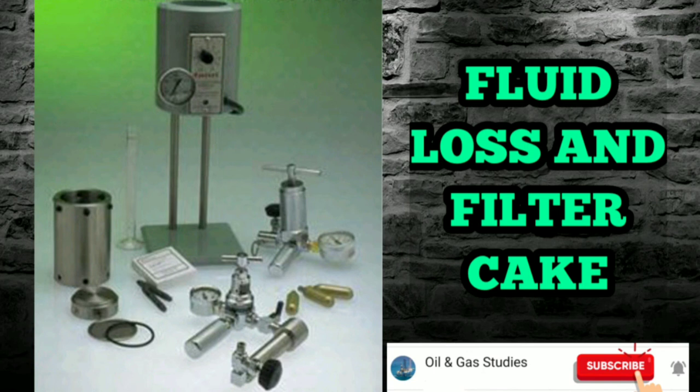Applications: the fluid loss gives a representation of the fluid's interaction with the well bore under simulated pressure and temperature conditions. Ideally, the fluid should form a thin, flexible, impermeable layer, filter cake, against the wall and prevent fluid, filtrate, from entering the rock and reacting with the formations. A mud system with a low value of filtrate loss causes minimum swelling of clays and minimum formation damage.